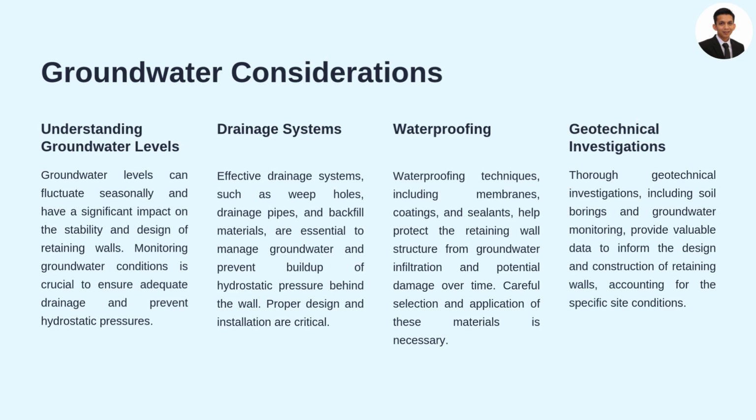Number 2, drainage systems. Weep holes and granular backfill improve water flow. Geosynthetic drains can enhance drainage in high water table areas. Number 3, waterproofing. Membranes protect walls from water ingress.